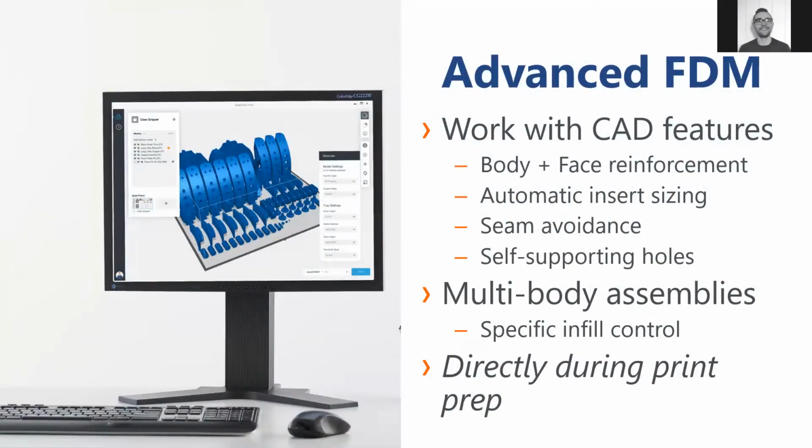So as mentioned, in advanced FDM, you can work with CAD features. So GrabCAD Print enables us to work with CAD, and because we're able to do this, when we're in advanced FDM, it can recognize particular features of CAD, whether it's a body, a face, a hole, a fillet, and then we can apply specific parameters to those features rather than globally to a layer that contains said feature.